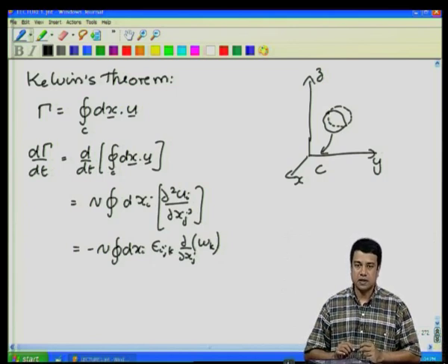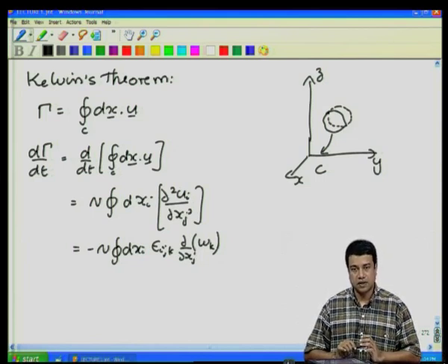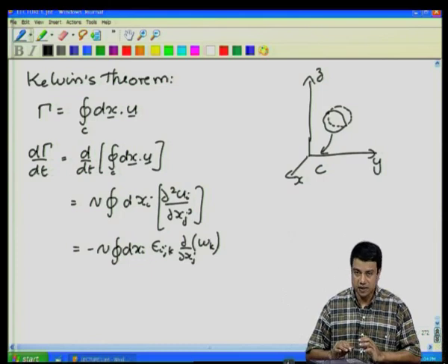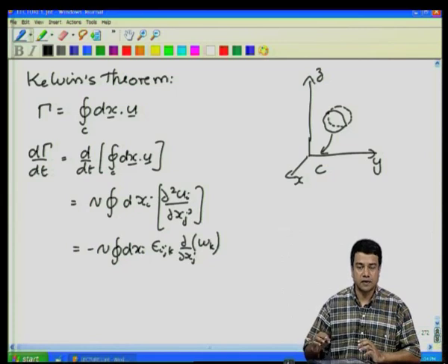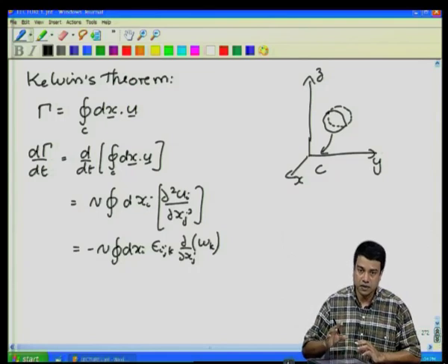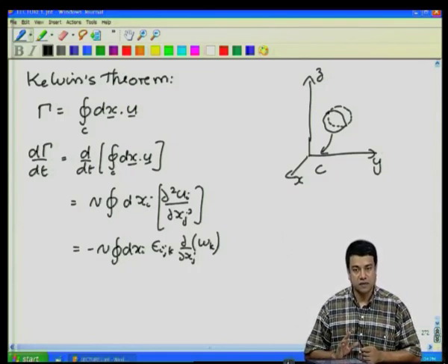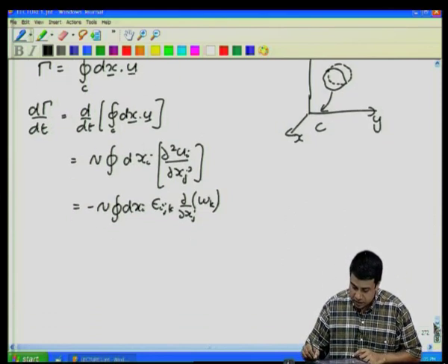The answer is vorticity is generated at solid surfaces, okay. And vorticity that is generated at the solid surfaces is then convected unchanged through the flow. The only mechanism of intensification is this mechanism of stretching and bending of vortex lines, okay. And of course, there is a mechanism by which vorticity is reduced, the vorticity diffusion mechanism. The rate of change of vorticity also has a diffusive term there, which tends to attenuate, to damp out vorticity variations. So, let us look at how vorticity is generated at surfaces.